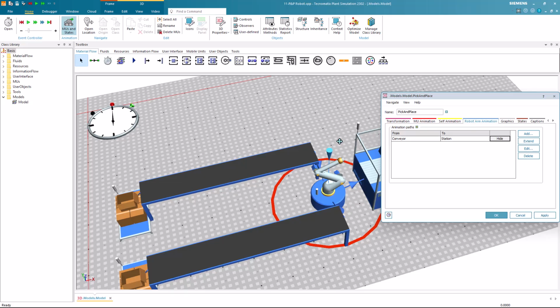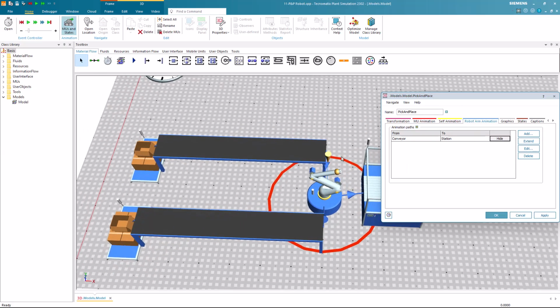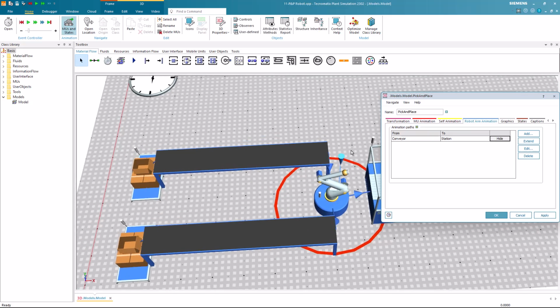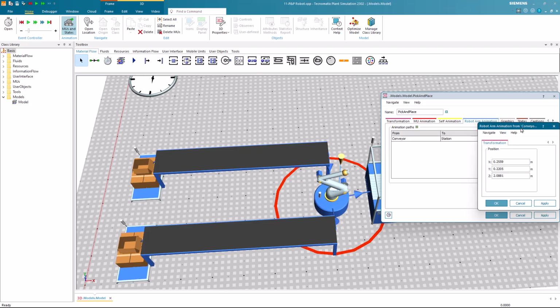Now we can select the cone and adjust the position by using the arrow keys. By holding the Shift key, the position will move by 1 meter steps. By holding the Control key, the position will move up and down. Or we can simply drag and drop the cone with the mouse. If you have exact coordinates, you can also double-click the cone and enter a specific coordinate.